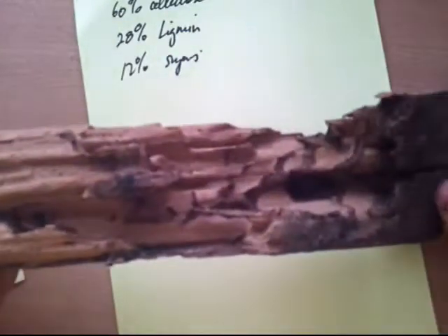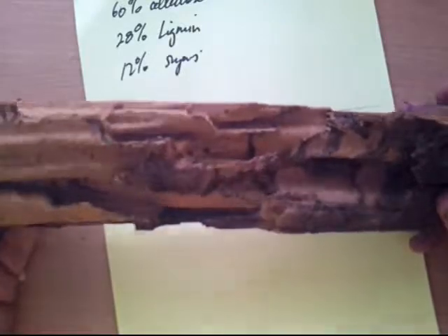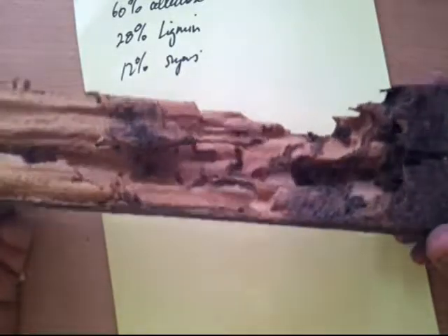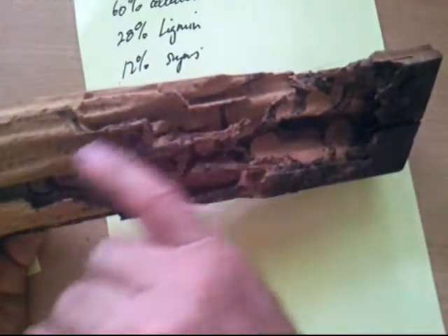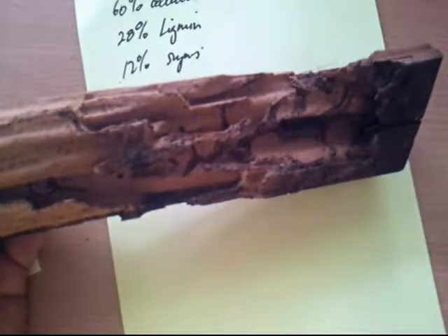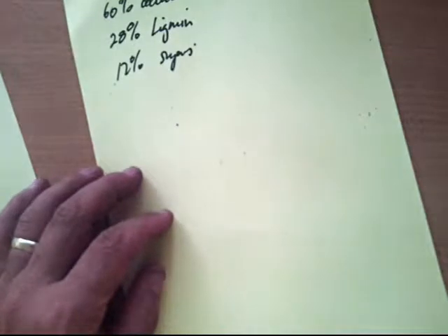It's also a renewable resource, so we can plant trees and grow them again, but it will burn, so not fire resistant, and it's subject to fungal and insect attack. So one of the problems with wood is that it is food for some creatures. White ants love it. This has been a white ant section of wood. It's Douglas fir, Oregon, sometimes called, housing type timber, and you can see how it's been eaten away by white ants. Fungus can also rot it, and there are problems associated with wood in that sense that it degrades.